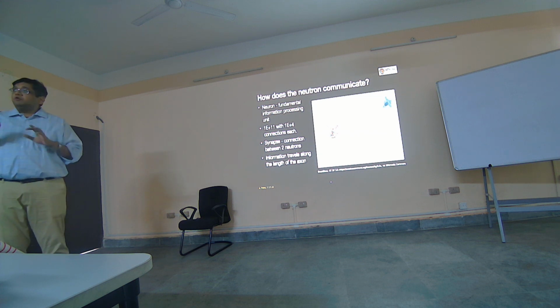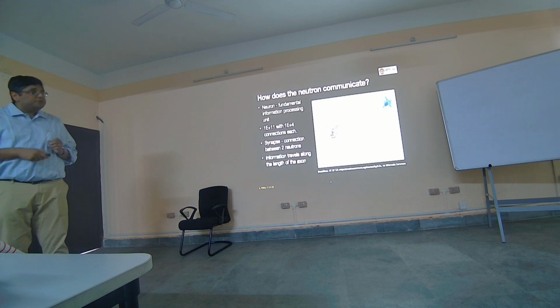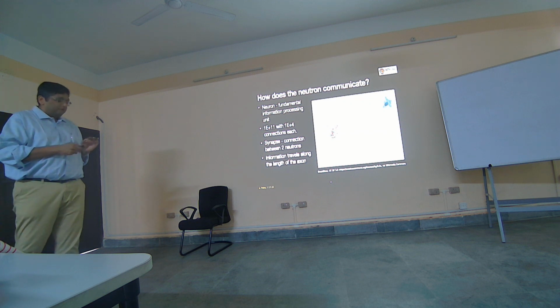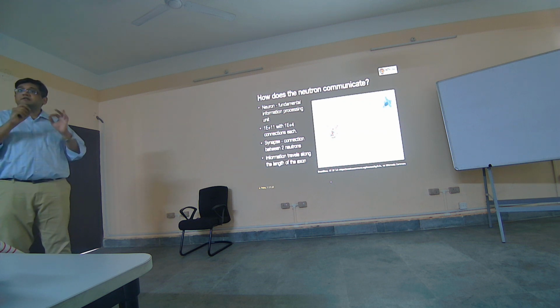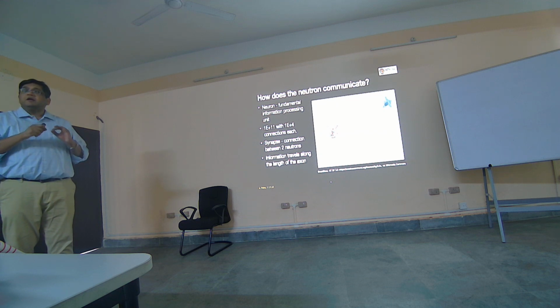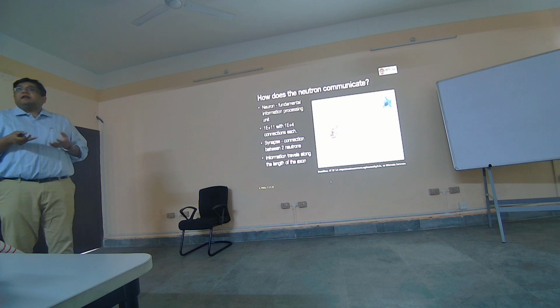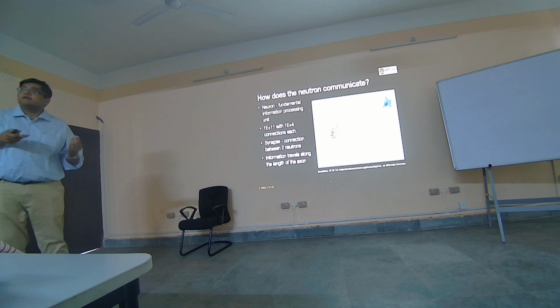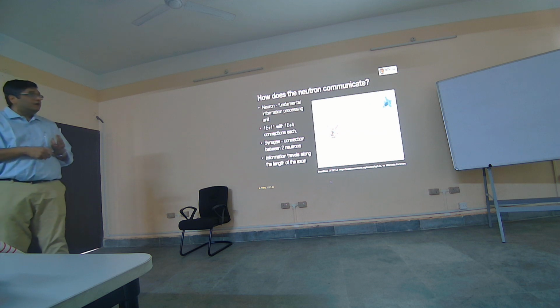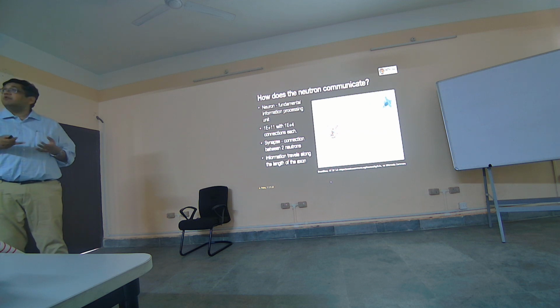And I'm not going to go too much in details of biology, but just to give you some numbers, we have approximately 1E11 neurons in the brain. Right? The big difference is that we have approximately 10,000 connections between each neuron. So if you think about a transistor, we don't have that kind of fan-out. Fan-outs in digital technology is roughly 10. In CMOS, you can go up to 15, right? But that's the fan-out limitation. That is the output of one transistor can maximum drive around 10 to 15 transistors. Whereas here, you can have connections which are way more than what you can achieve in silicon.